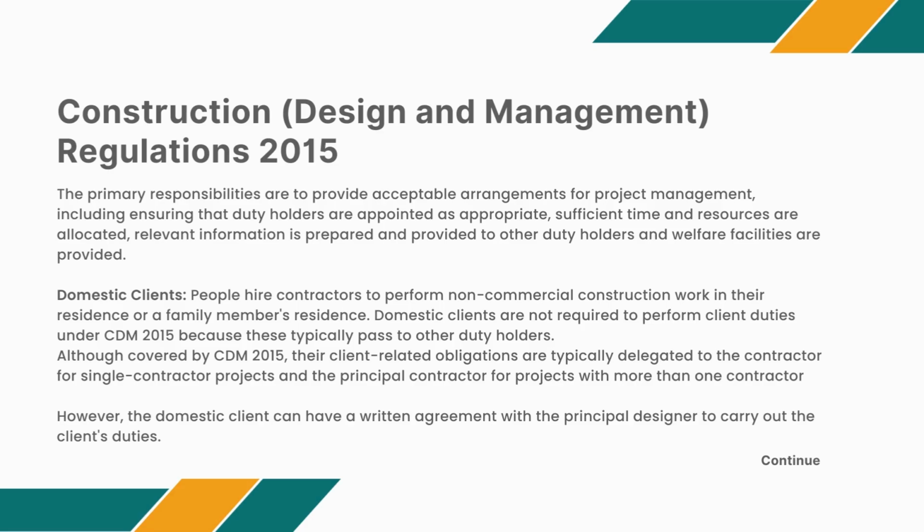Domestic clients: people who hire contractors to perform non-commercial construction work in their residence or a family member's residence. Domestic clients are not required to perform client duties under CDM 2015 because these typically pass to other duty holders. Although covered by CDM 2015, their client-related obligations are typically delegated to the contractor for single contractor projects and the principal contractor for projects with more than one contractor. However, the domestic client can have a written agreement with the principal designer to carry out the client's duties.